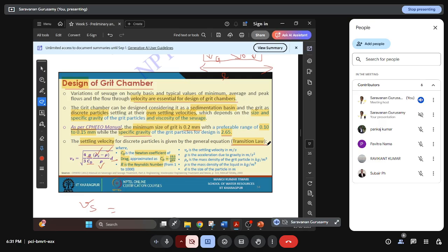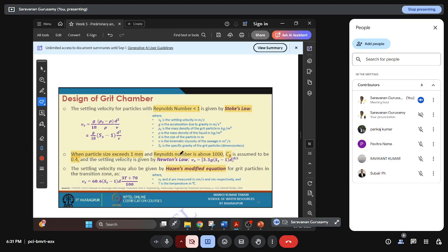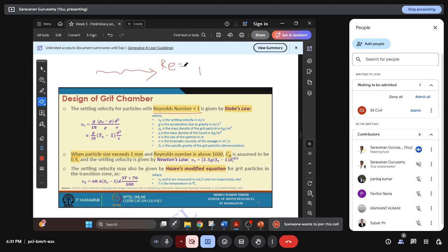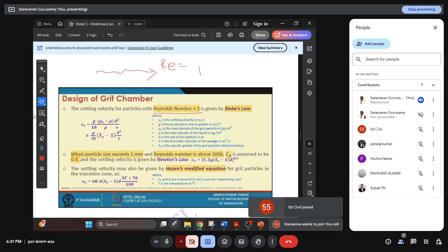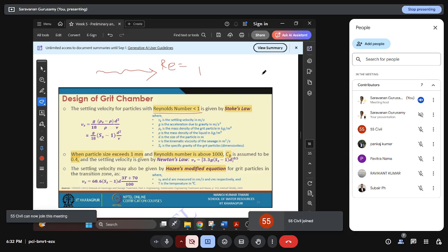The flow is either transitional, or non-transitional, that is laminar. You all know about hydraulics, right? When the water is passing, you can find the Reynolds number of the flow. If it is a laminar flow, it is slow movement, with no turbulence. If it is turbulent, it has higher velocity and turbulence.